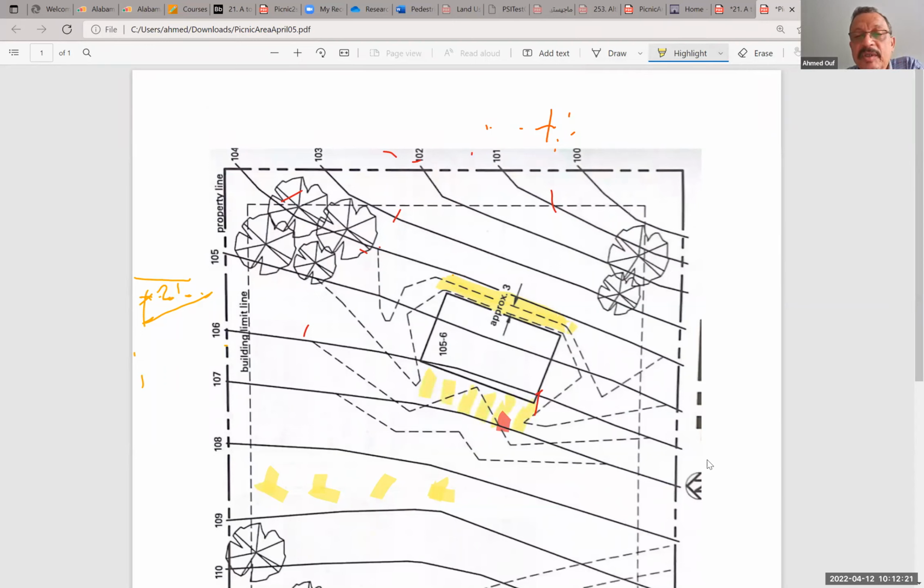So again, I'm gonna do the whole thing, just summarize it. We have water coming from that direction because this is the high point of the site to the lowest point of the site. So water will want to go in that direction, to go down and lose energy with inertia. It comes here, and then I have an issue with water that might collect in the front of the building. It might also collect in the back if it is completely flat or something.